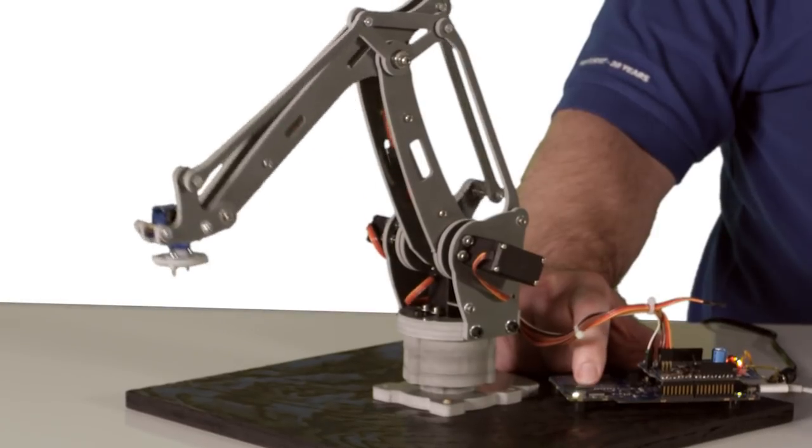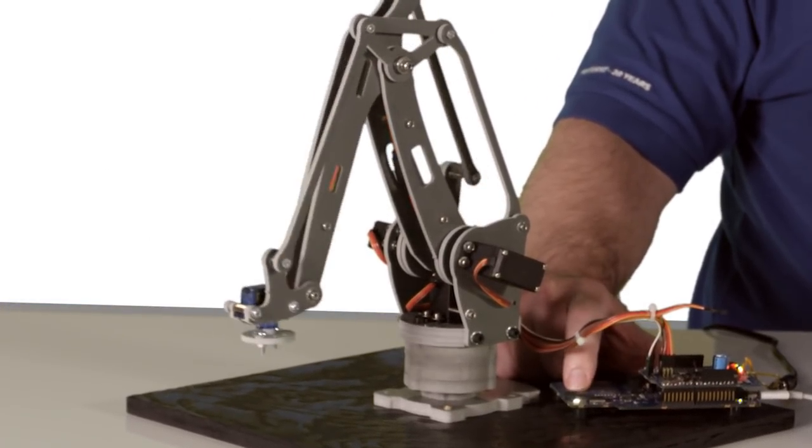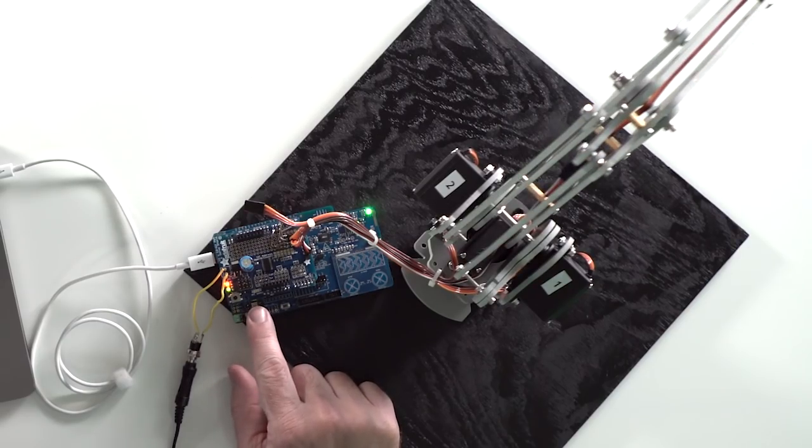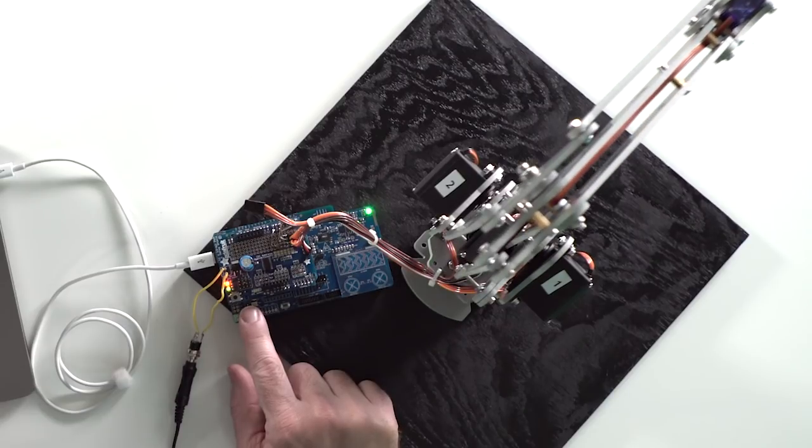For our BLE-controlled robotic arm project, however, I'm going to dedicate the Cortex M0 Plus core to be the BLE connectivity tasks as well as the security tasks that I'll teach you about in a future video. We'll use the Cortex M4 core for the rest of the application, and that means driving the servo motor PWM signals. It means reading from the digital sensors, like the motion sensor, and it includes outputting the data to the e-ink display. This architecture is very configurable, so depending on your architecture needs and your application problems, your implementation may differ slightly, but I'm going to show you how to work with each core independently so you can customize this thing to your own needs later.